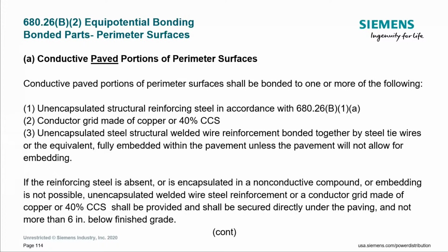We can do that. So basically, you can extend it out from the pool, out over the coping, and take it out 3 feet if you wanted. A piece of rebar, bend it out, curve it out, continue it on. Absolutely. And another straight piece can tie on it by a simple steel tie wire to extend it out. Okay, that can be done. Can you put that grid? Well, if it's okay for the conductive pool shell, it certainly should be okay to do this as well.